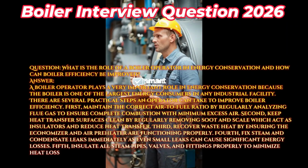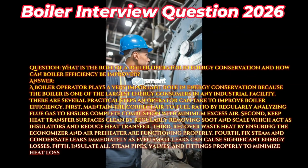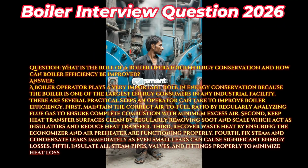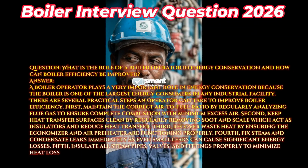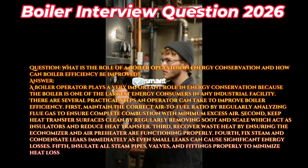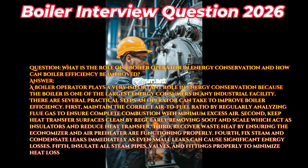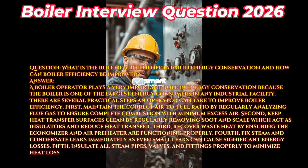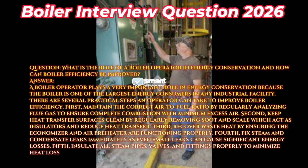First, maintain the correct air-to-fuel ratio by regularly analyzing flue gas to ensure complete combustion with minimum excess air. Second, keep heat transfer surfaces clean by regularly removing soot and scale, which act as insulators and reduce heat transfer. Third, recover waste heat by ensuring the economizer and air preheater are functioning properly. Fourth, fix steam and condensate leaks immediately, as even small leaks can cause significant energy losses. Fifth, insulate all steam pipes, valves, and fittings properly to minimize heat loss.